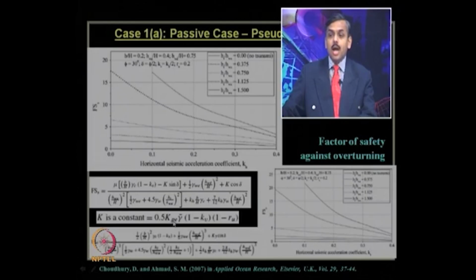Kpe you can use the Mononobe-Okabe or any other pseudostatic seismic passive earth pressure coefficients, and all the others are non-dimensional terms of ratio, that is HWD by H, that is height of the water table with respect to total height of the wall, Ht by Hu is the tsunami wave height over the static still water table level.